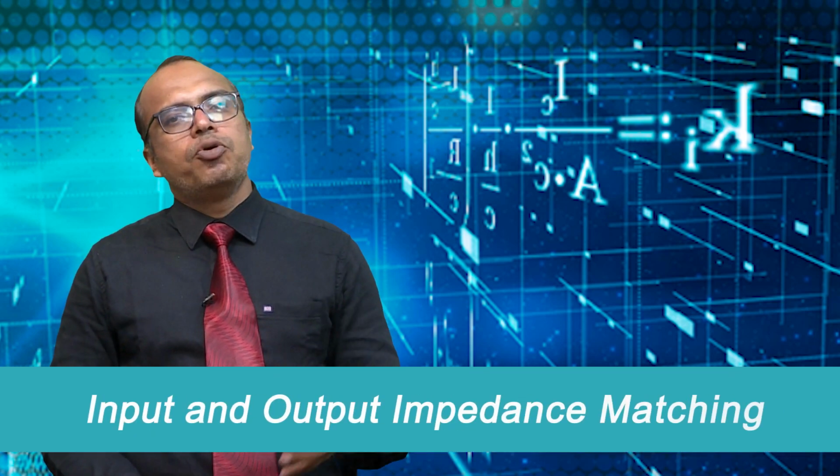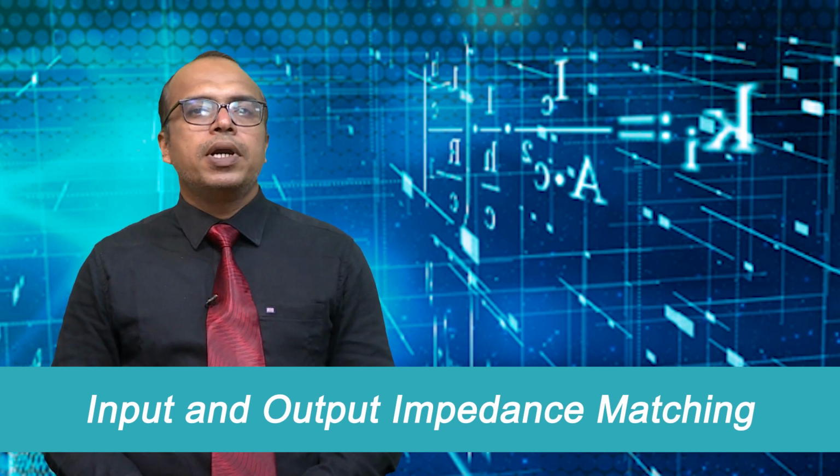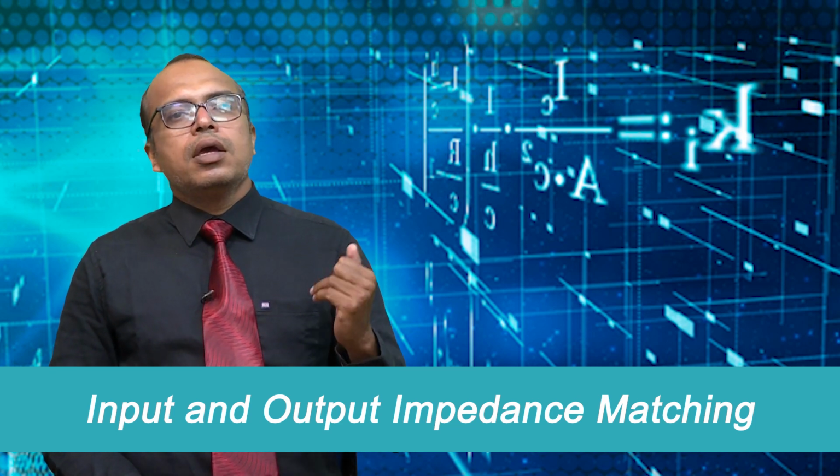of the multiplier circuit. The next point is input and output impedance matching. Mismatched input and output impedance can lead to signal reflection and loss of power in the circuit.